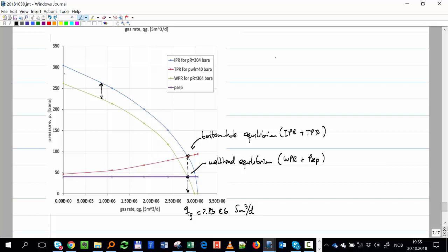Remember, that's why it's important to look at the wellhead, how it looks. We have this collection of valves, right? And then there is something we are missing here, which was very important in our drawing: the control element. That was the choke. So here you have P separator, and here you have P wellhead. So far we are assuming they are the same. The pressure of the separator is the same as that pressure because there is no choke.